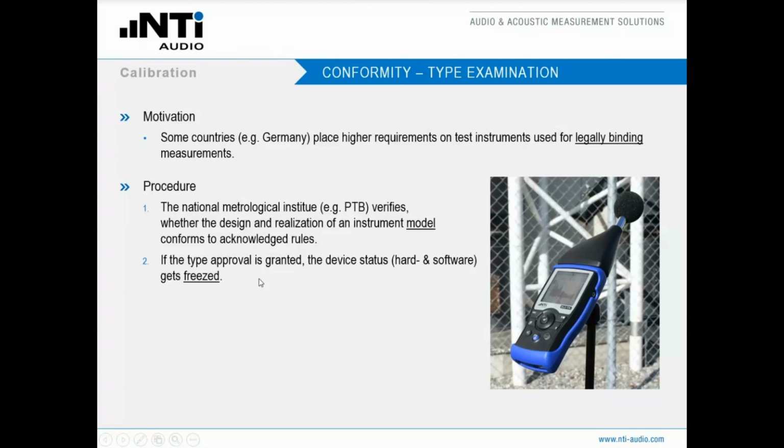So there must not be made any change to that instrument or to that model, otherwise it would lose its type approval. So these type approved instruments must also be sent regularly to accredited calibration labs for calibration. So with this procedure, you make sure that your instrument is working properly and that you can use the acquired results in a court case as an example.